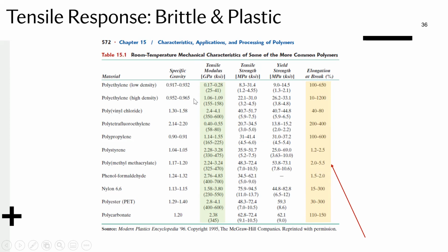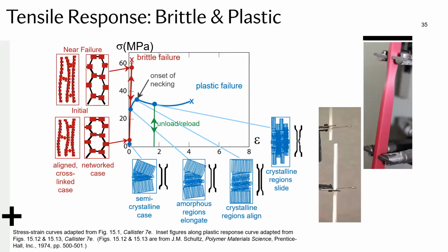Okay. Versus where you have 0.1, 0.2, you would expect the stiffness, the slope, to correspond to those materials that have more of a plastic behavior. And you can see it here. I'm going to go back here real quick. What I'm talking about is the slope at the beginning. And you can see that it's pretty steep, especially if you compare it with elastomers, which we had.